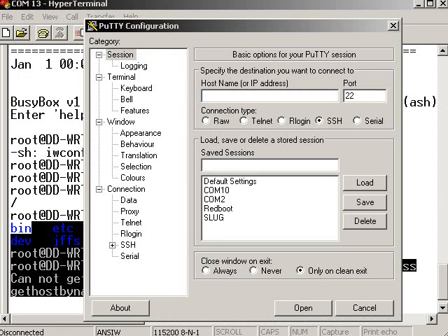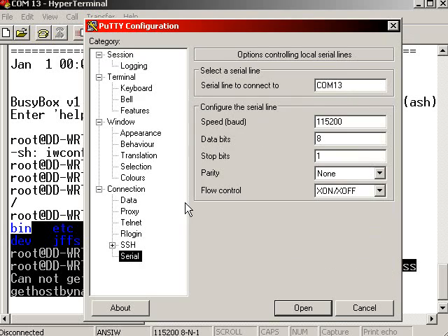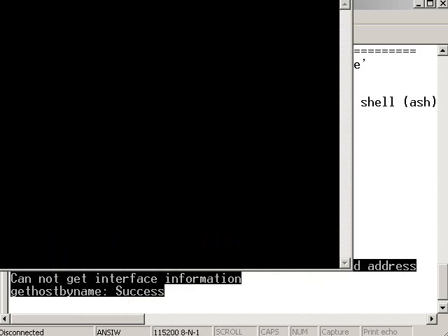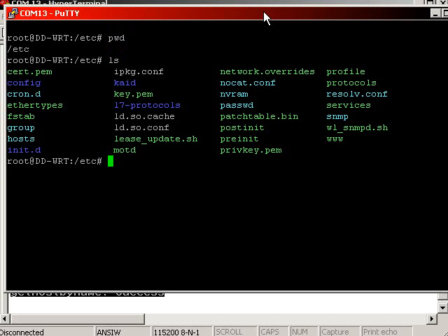You know what? Before we even move on to SerialMon, later versions of PuTTY, the secure shell client for many operating systems, have serial capabilities. Just make sure you put in the proper communication protocol, 115200. Now you can go to the serial tab down here. Make sure you have proper flow control. Click open. Will it give us a shell? There we go. Not much more to say about that. PuTTY can also be used to directly communicate with your serial port.